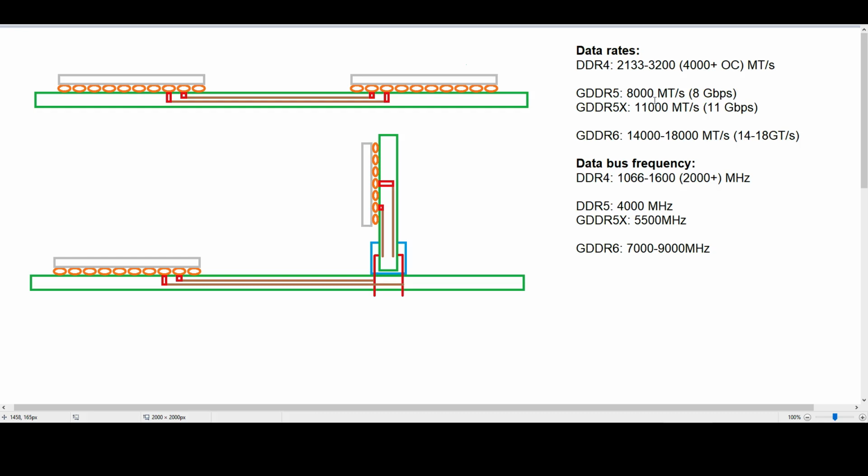So rather than saying a 1 or a 0 in terms of the voltage representing a data bit, we represent the data bit in terms of the change from the 1 to a 0. So we can do that twice in every clock cycle. So that's why we have the double data rate thing, where the actual operating frequency is half of the data rate.